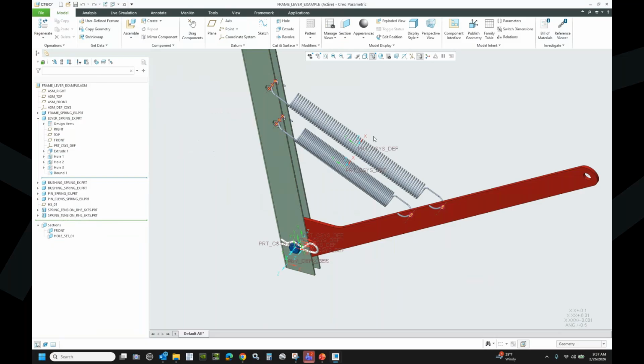And that's what you have to consider. If I go this far with it, I'm probably not adding too much to the wire length. We could probably measure if we wanted to, but I'm not making it be that much longer. If I were to make that spring stretch, it's probably the wrong size spring, right? So I probably have to go up to the next size spring. But to answer your question, yes, I could add that variability if I wanted to.